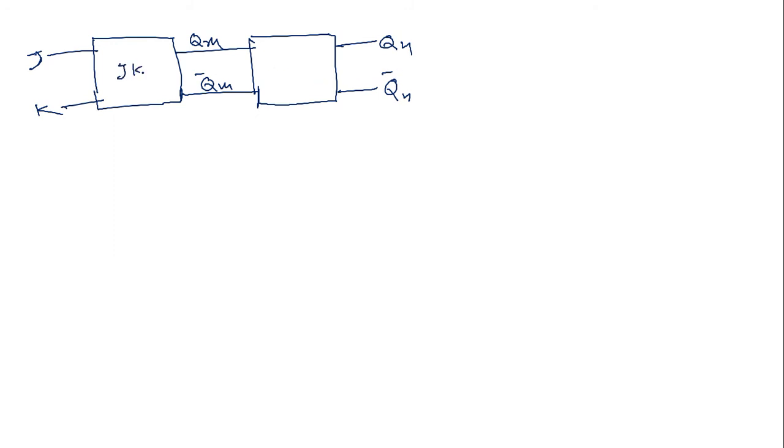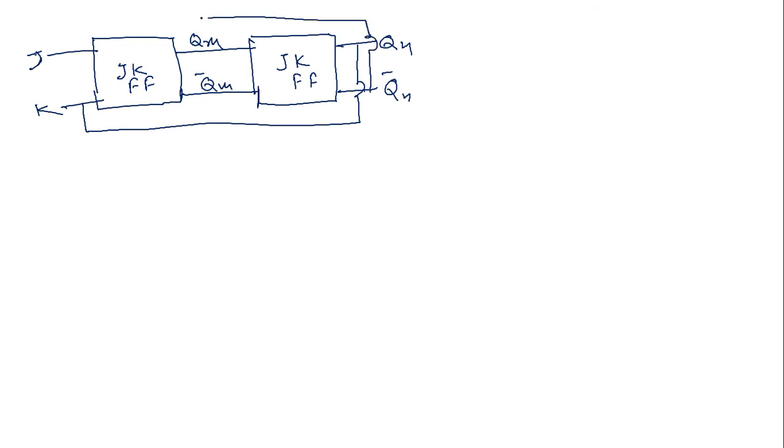One feedback path is connected from here, because this is a JK flip flop concept. Now this is a master slave JK flip flop, and one thing is left, that is the clock. One NOT gate is present in between the clock pulse of the two flip flops.